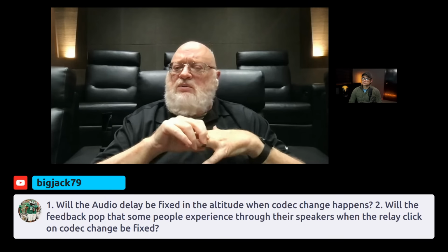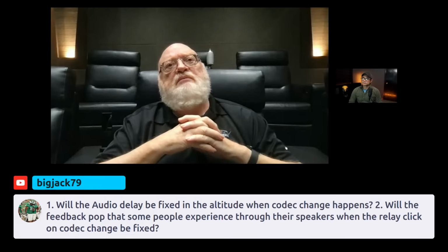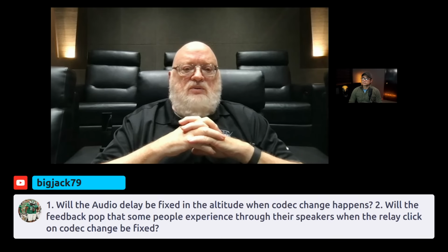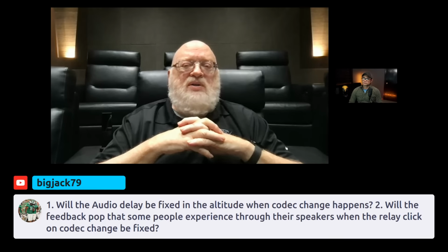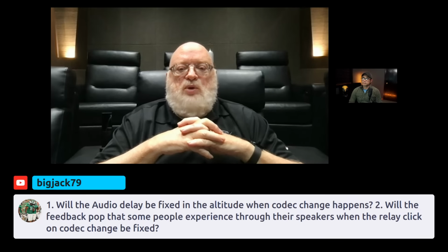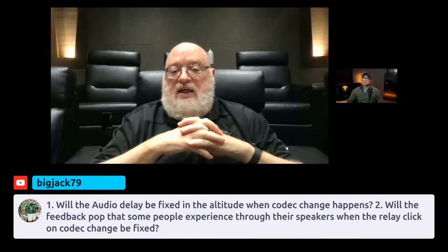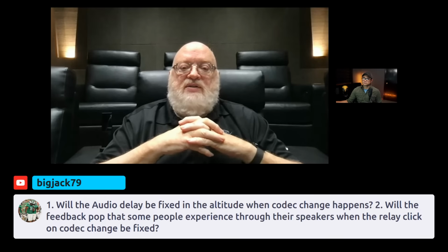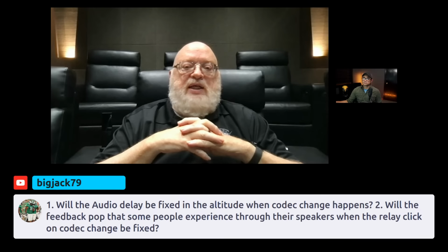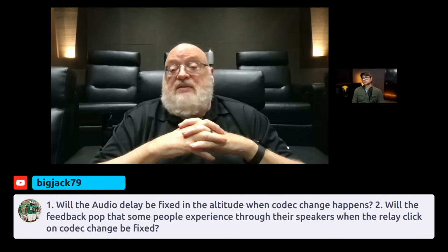And that relay question has now been moved into the Amplitude 16, because that's where the D-to-A conversion is done. So I don't know exactly how that's been handled on that board. I would hope that the problem has gone away with the CI, and we are working on changing the timing a little bit of those relays to see if we can eliminate the oddball systems where this is happening.